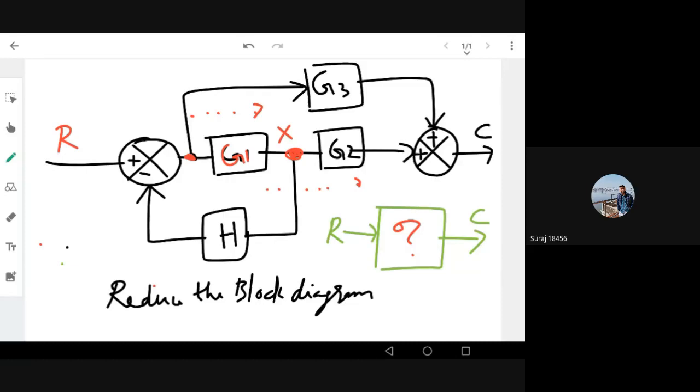Right now there is no multiplication possible. Here also in this loop you cannot directly take the feedback transfer, because there is a loop going here. If I simplify here, the signal input to G3 will also change, right? You cannot combine these two and make a simple block diagram. So we have to think a bit. What is the net block diagram here?